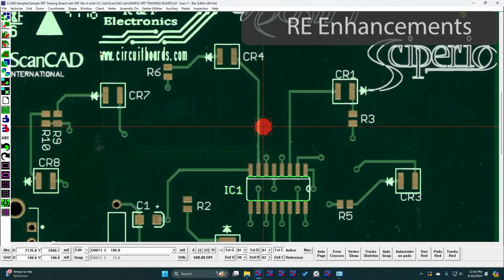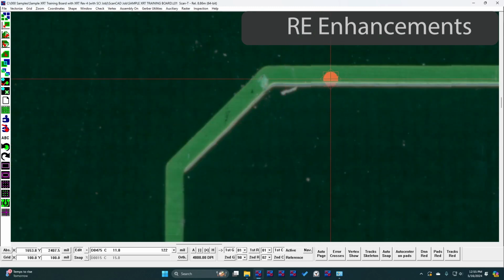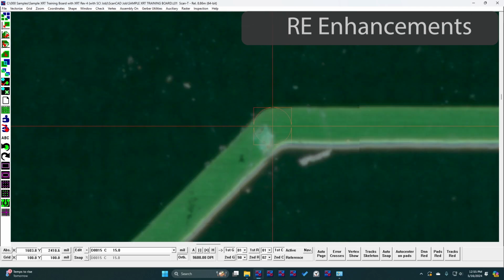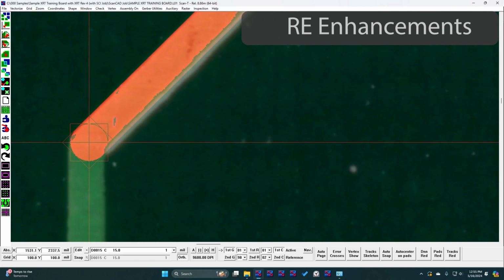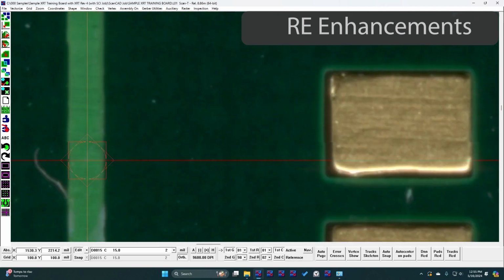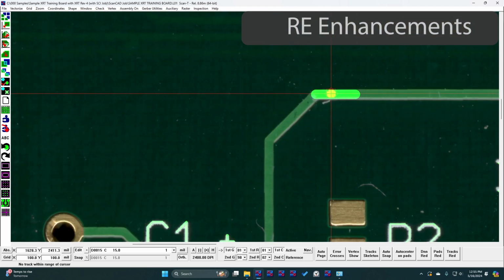And this really helps when you're drawing tracks or creating contours, because you don't have to pretend anymore. You don't have to guess what the right position is in order to change angles. So for instance, if I want to catch this orthogonal line here, all I need to do is line up that top diagonal angle of my guide and then go, and it's perfectly aligned. Now again, I need to align that vertical angle on my cursor and go. And so it just makes manually drawing tracks when you need to do that significantly easier.